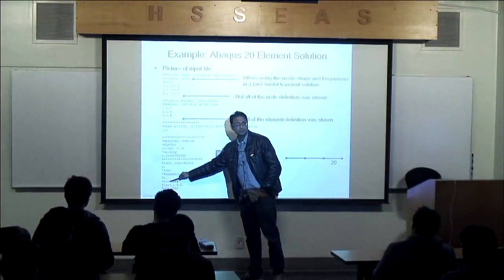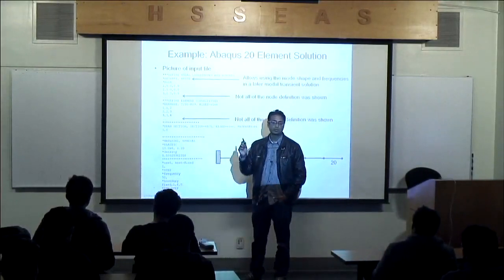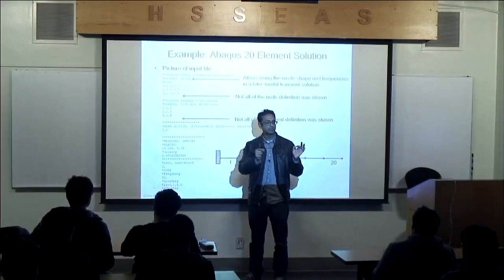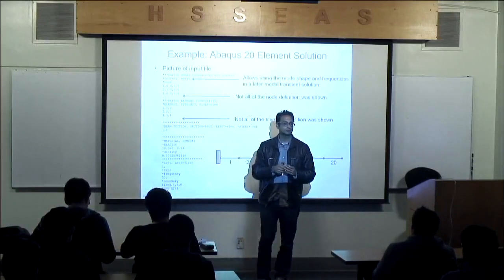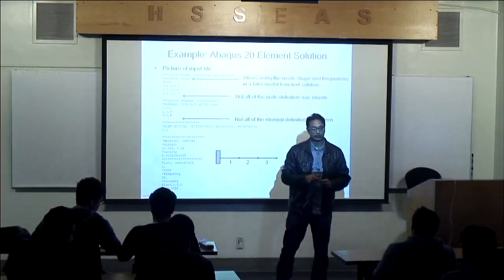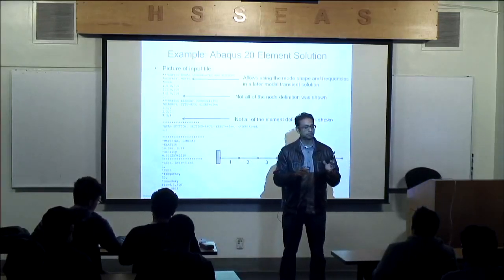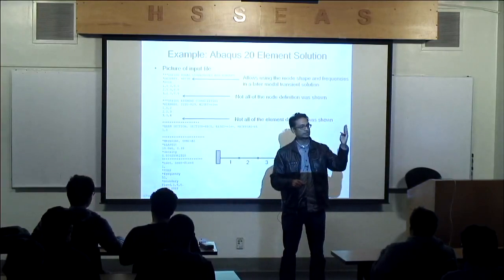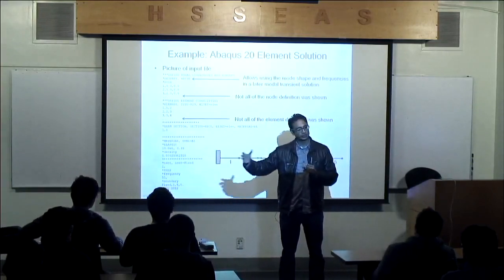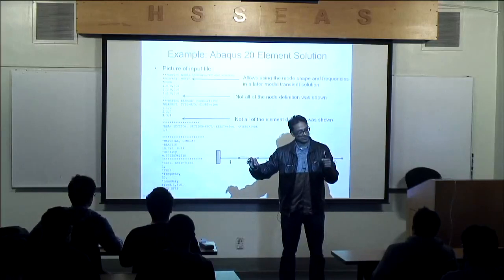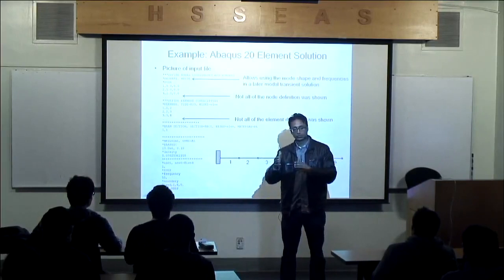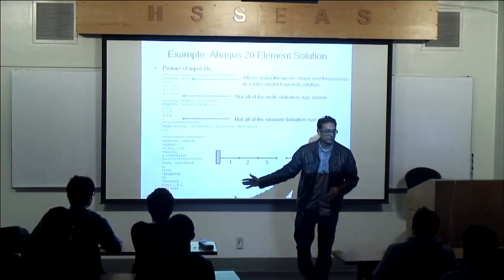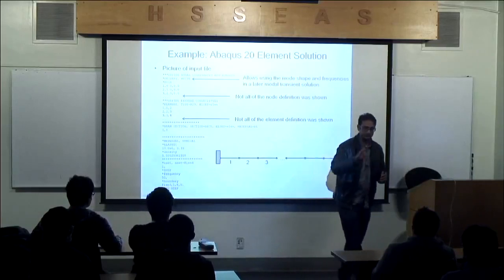I think I did 50 and it was fine because this Euler-Bernoulli beam has axial flexibility. And so now I have 3 nodes, I have 3 degrees of freedom per node. So I will have about 60, don't quote me on this, but you'll have 63 degrees of freedom. The left-hand side is fixed, so you have 60 degrees of freedom really, because you have axial flexibility. Okay? Our formulation that I just discussed does not have axial flexibility, so we're going to have 40. But yeah, I asked for 50, but I didn't plot all of them. I just focused on the first couple of them.